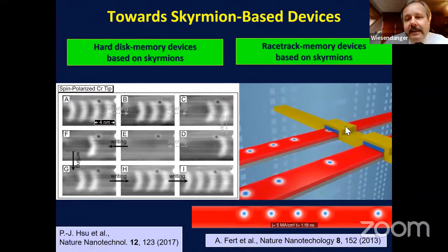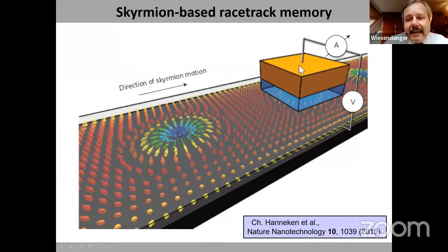Now, the problem is that if you use a magnetic tunnel junction with a magnetic top layer to detect the passing of a skyrmion, then this magnetic layer creates a stray field on your magnetic storage layer. We have basically calculated this effect and found that for the magnetic layers we wanted to use, this magnetic stray field would be much too large.